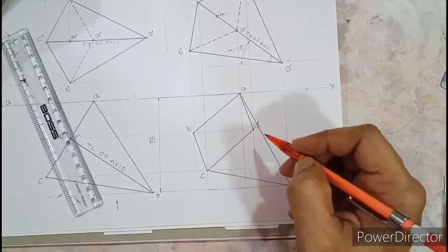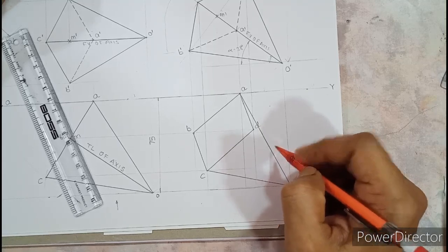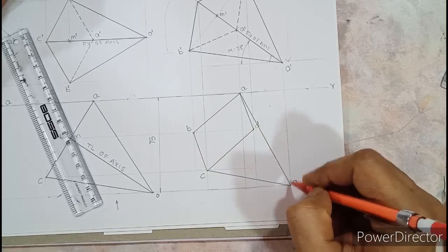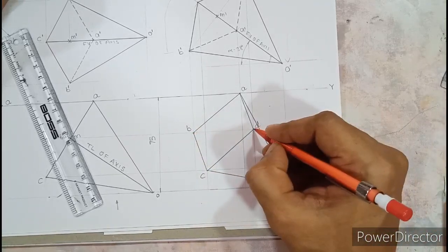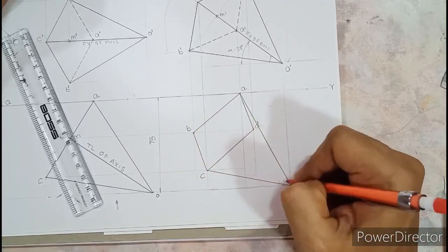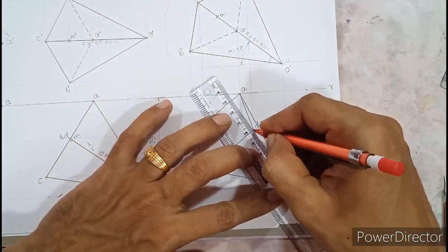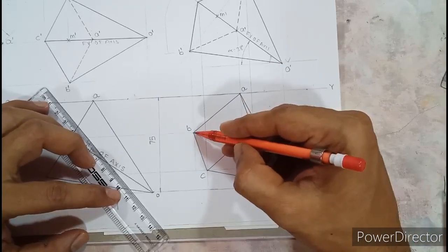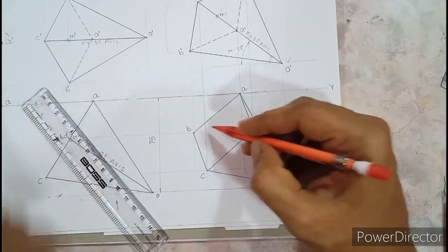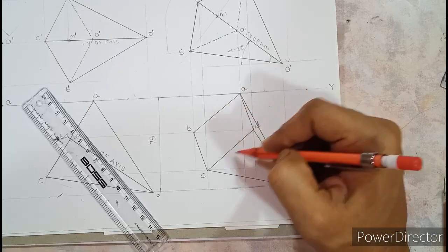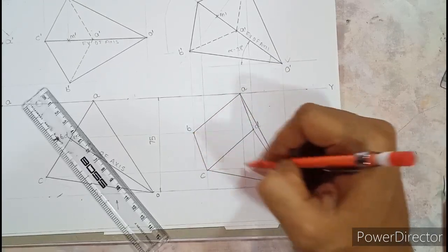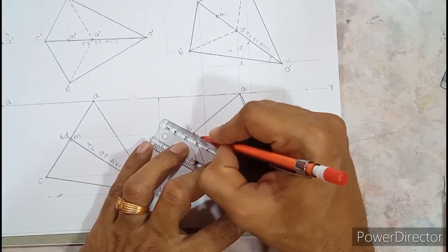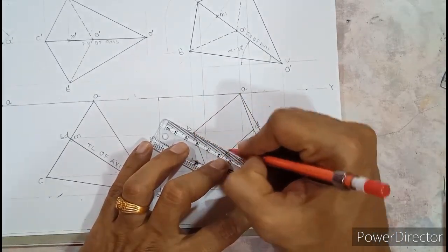Now next step is, in case of square pyramid, there should be 4 slant edges. You have drawn only 2, O to A and O to C. Two more are left, O to D and O to B. So from dark corner of the base, draw dark slant edge. So D can be connected with O. But B is also a dark corner. We can't draw dark slant edge because a dark line cannot pass through a visible base. Also, two dark lines should not cross each other. So from B to O, we have to show hidden. So we'll draw this hidden.